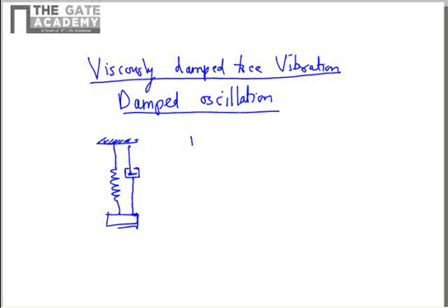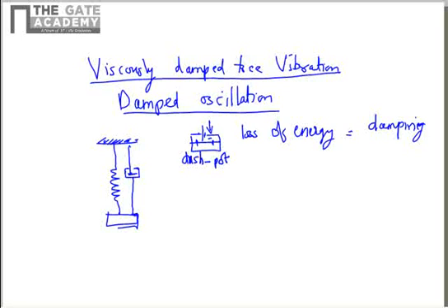The dash pot in application is a pot with a piston inside and some orifices and a fluid inside. So when the piston moves, the fluid goes from one side to another, and it results in loss of energy. So damping means basically loss of energy. This you are modeling by adding a dash pot. Like the spring mass is a representative of any system which is having flexibility to come back to equilibrium position and having inertia, similarly, dash pot is also representative of any damping.